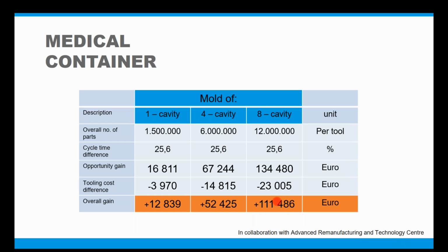But I think it's important to remember that you don't always have to increase your production, but maybe you can use fewer cavities. So maybe now they can go for 4 cavities instead of choosing 6 cavities or something similar to that. So it might also mean that you can produce your parts faster or with fewer machines. That's also something to have in mind.